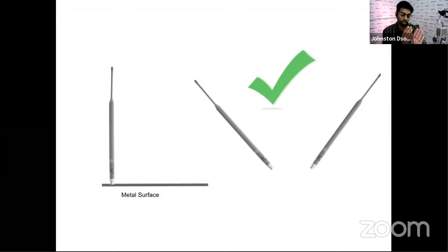So in that case, if you do not have space on your stage, you make sure that you put the IEM antenna in front and keep the microphone antenna behind. But then also there has to be some distance between them so that they don't interact with each other. If you have space, then probably space them out properly.